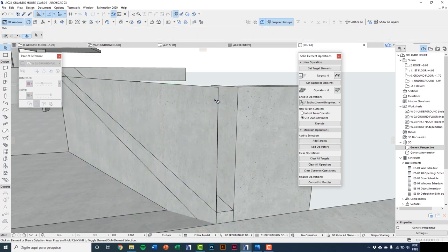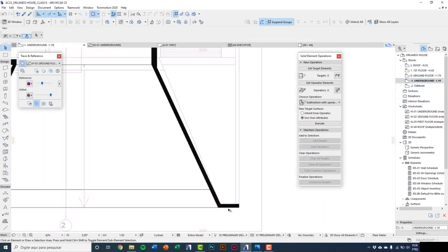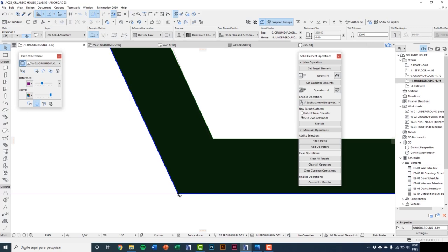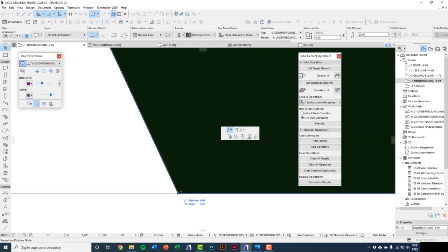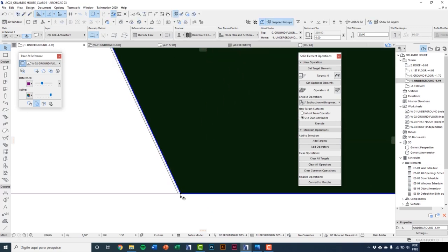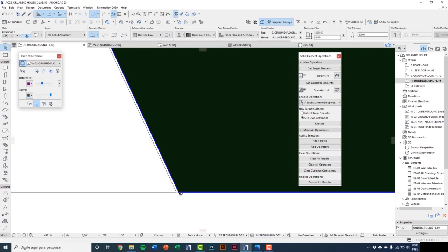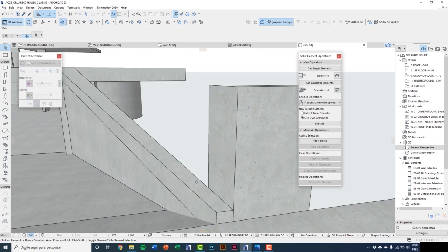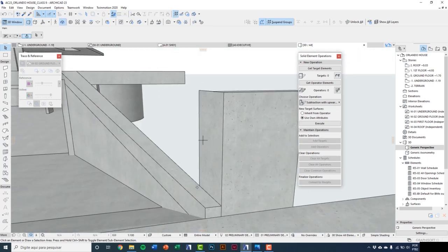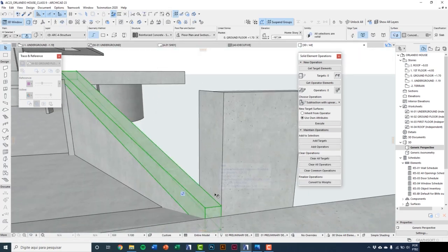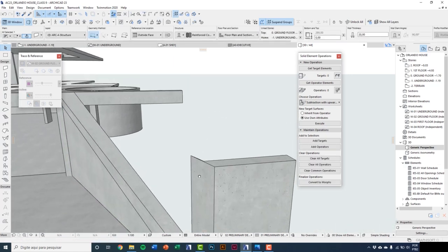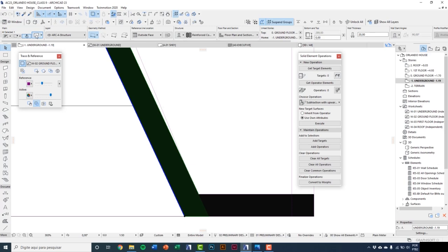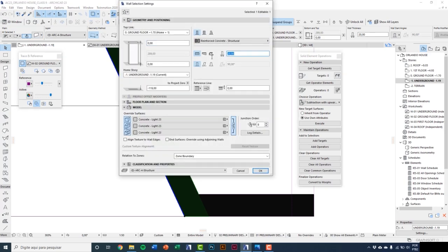So here in this wall, on the ground floor, I'll select the two walls, clicking on node. I can do a height adjustment. This position. So on 3D, you can see that now the elements are being cut correctly, but here still there is a piece. So again, this wall I put 18 centimeters thickness.